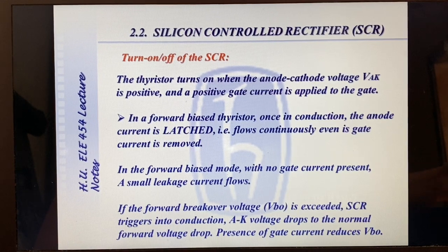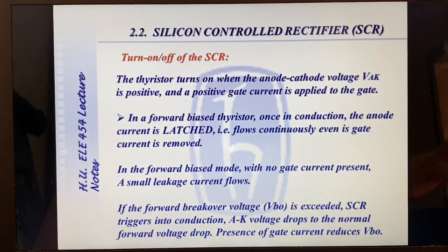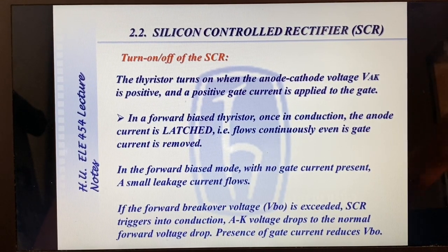It controls itself. The intrinsic gates in the parallel operating thyristors within the chip are triggered with the previously conducting thyristor, so that they do not cease conduction.